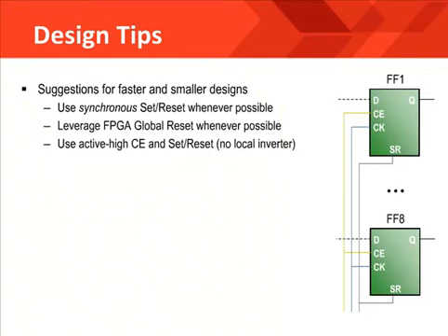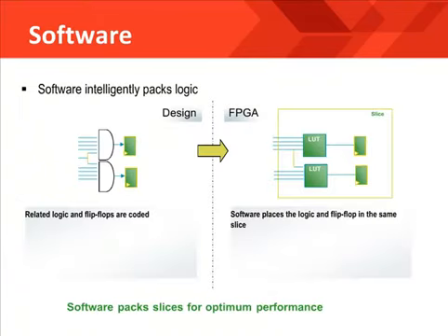And don't forget to keep your control signals active high, so you don't need a local inverter to be mapped to each control signal input. These are not dedicated in the silicon, and that would force the synthesis tool to waste a LUT input. The reason we have spent some time discussing the limitations of control signals is that they can limit your ability to get high device utilization and high speed out of your FPGA.